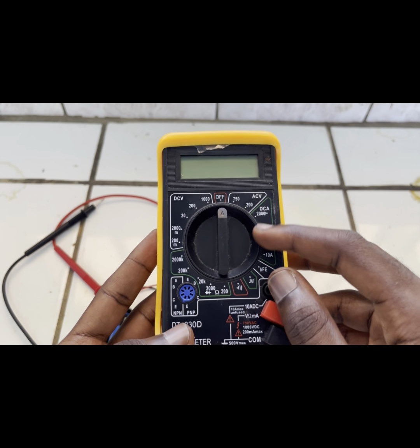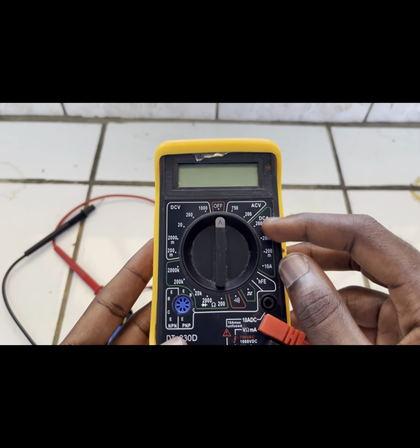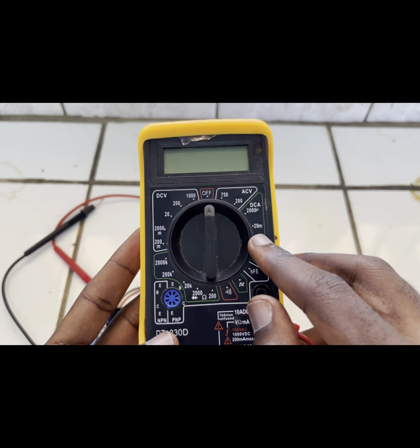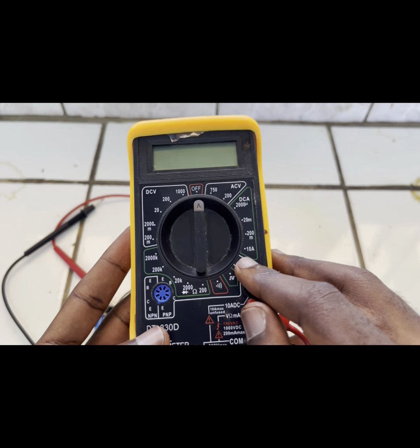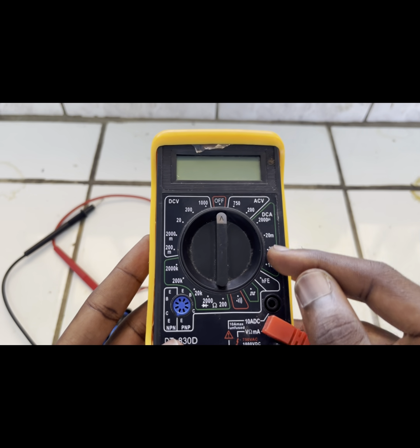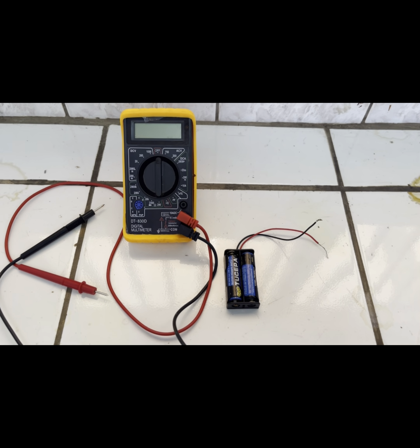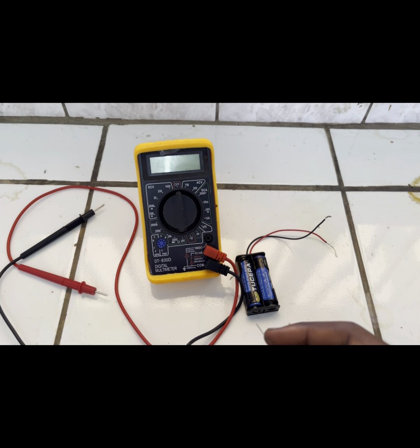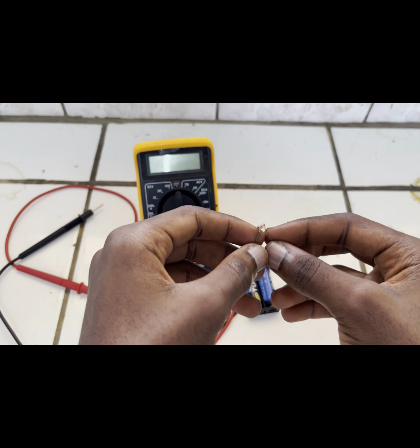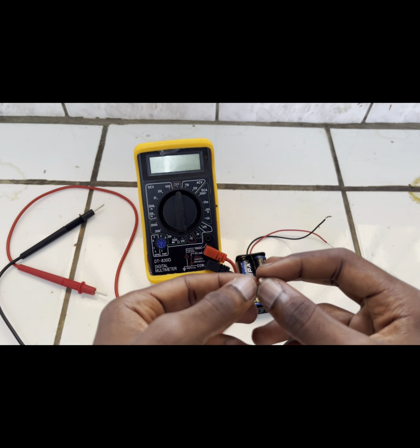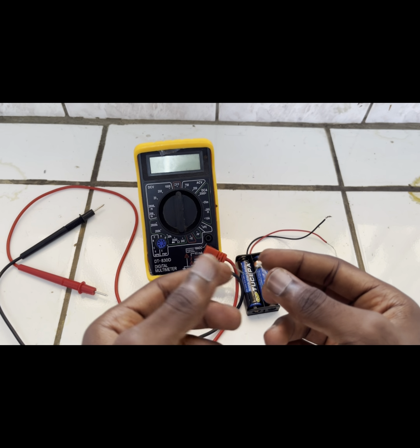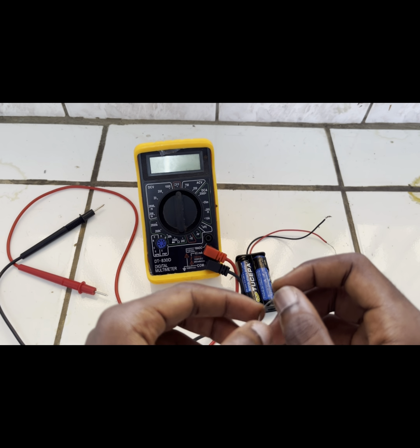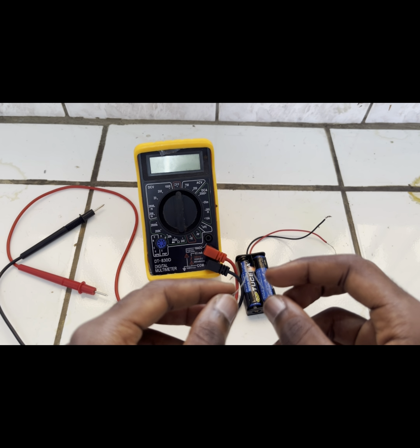Here, this DC, we want to measure direct current. You are seeing here 2000 micro, 20 milliamperes, 10 amperes. So these are the different calibrations. Okay, so in this station, the multimeter is being used as an ammeter. It means that you want to measure the current flowing through component H. So you want to compare, when component H is exposed to light, how does the current vary, and when component H is not exposed to light, how does the current vary. That is what you want to do here.